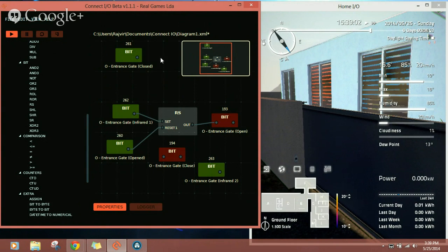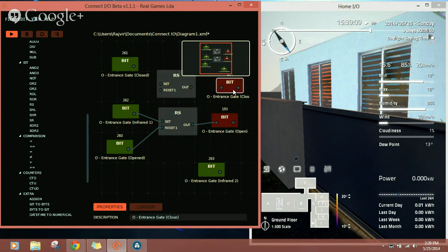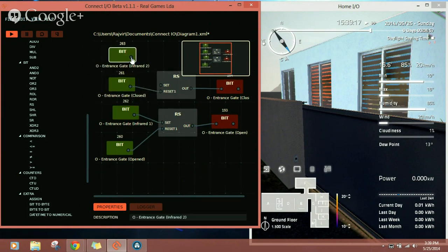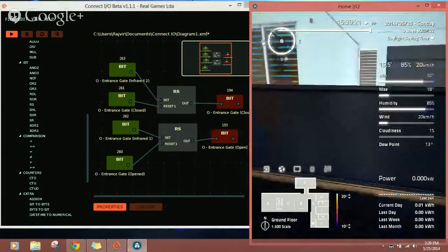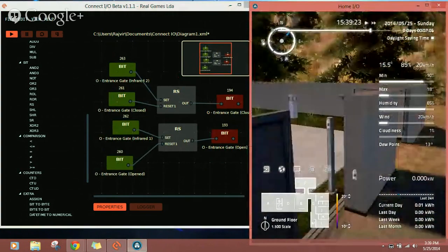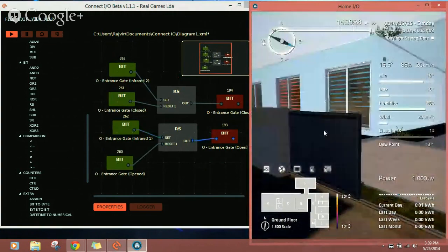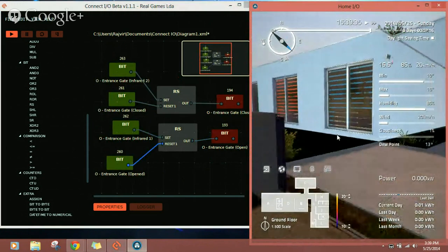All right. Similarly, we'll do the same function. We can do the copy paste operation for the gate close as well, like this. This will be reset. Sensor 2 will be set. Now let's see an example. I'll just go in front of the gate once. Now even if I turn back, this will remain on until the gate is 100% opened. So this is how we just automated the front opening operation of the gate.